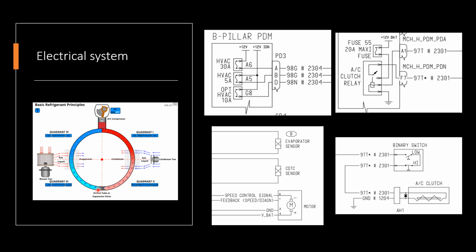And you need to be able to separate these 2 systems in case you're going to diagnose them or troubleshoot. So if your blower motor's not working, it can cause discomfort in the cab because your AC is not working, but now you have a blower motor situation. You have an electrical system malfunction, and so it has nothing to do with the refrigerant system.